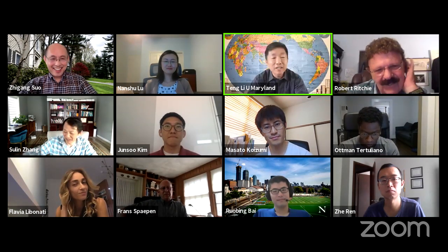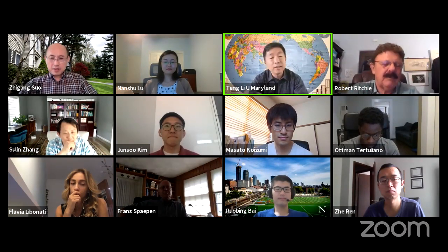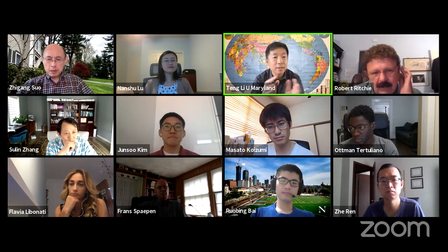So I have a question about the later part of the talk on this high entropy alloy. You showed in this paper last year, a Nature paper, that we replaced the magnesium with the palladium, right? So the distribution of the atoms, the elements in the alloy, becomes quite different, going from a rather uniform distribution to a somewhat inhomogeneous alloy with this magic number of about 1 to 1.4, 1.5 nanometer